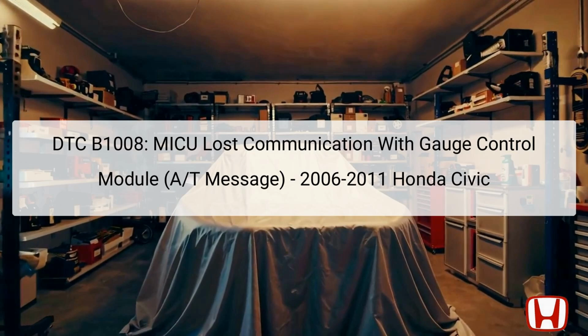The Diagnostic Trouble Code, DTC B1008, is triggered when there is a failure in communication between the Multiplex Integrated Control Unit, MICU, and the gauge control module in the vehicle. This issue typically affects the dashboard's ability to provide accurate vehicle performance data such as speed, fuel level, or engine temperature. The MICU is located in the under-dash area and serves as a central controller for various electronic systems, including communication with the gauge control module.